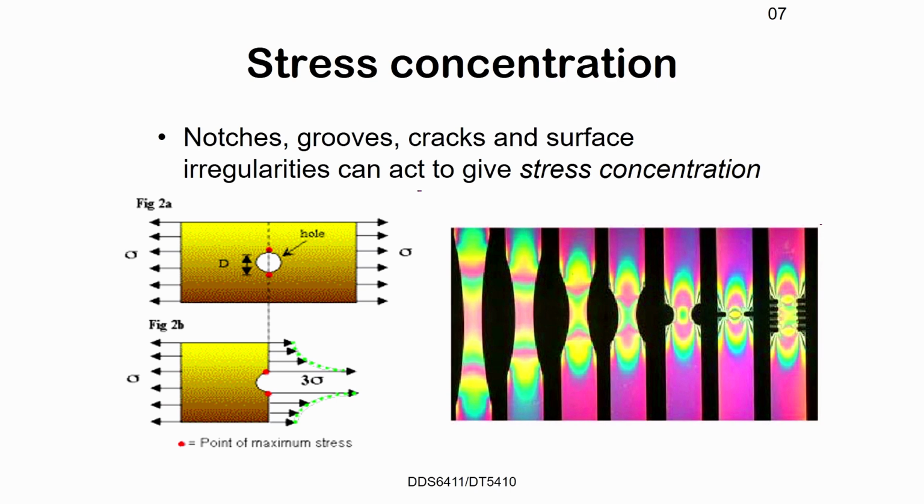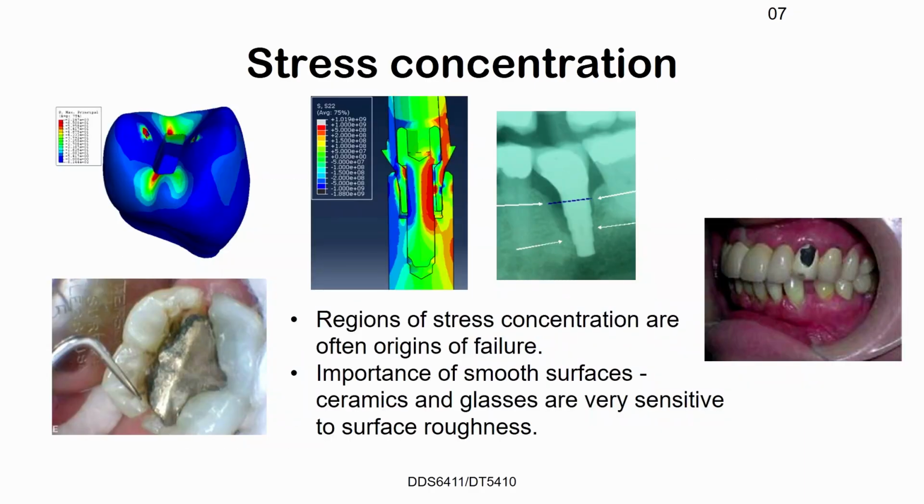So remember, stress is force divided by area. You have a smaller area, same force, so there will be an increase in stress intensity. And the important thing to recognize is that most failure, as we mentioned, would start from stress concentrations.